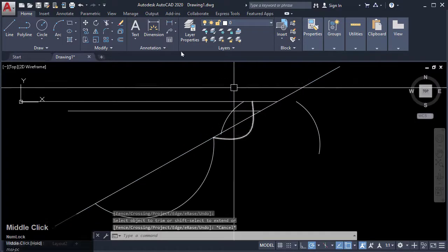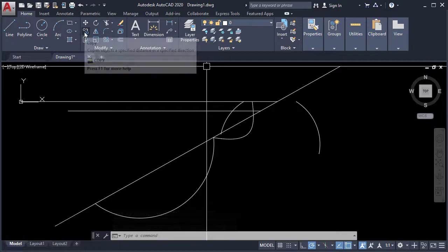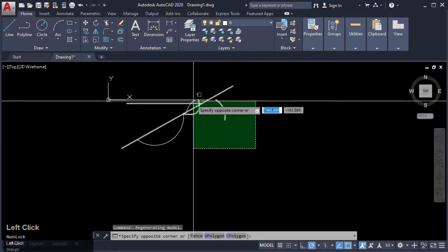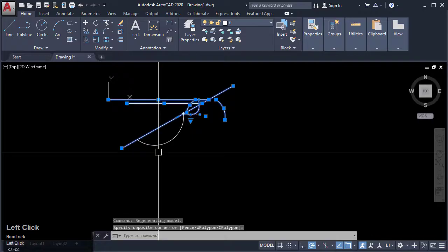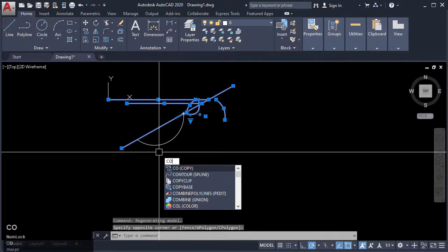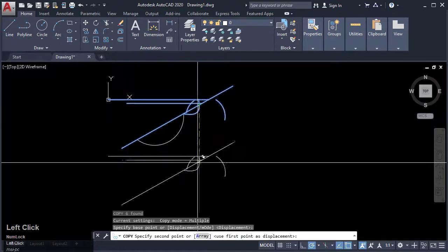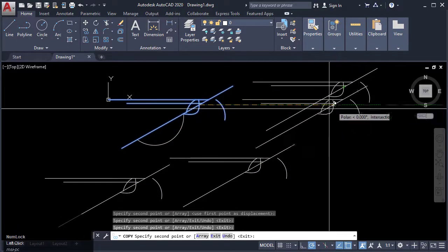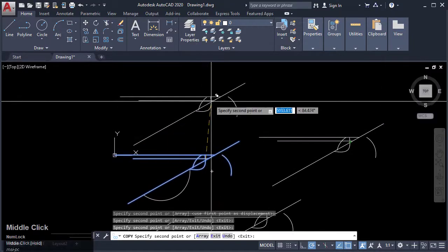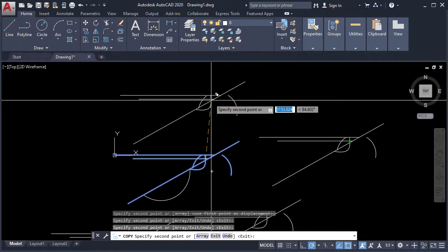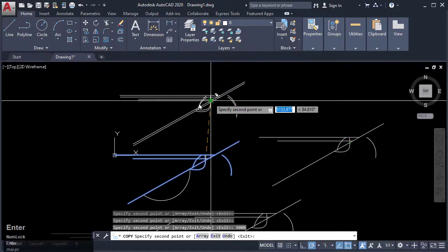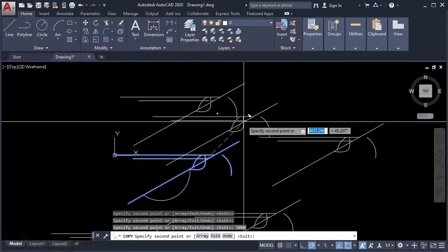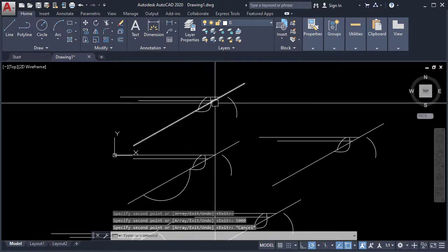Another thing that we can do is we can use the command copy. So if I select an object, then type in the word CO, enter, I can click and drag and click towards the desired location, or I can type again the distance of where I wish to direct my object. So I type in 5000 towards the direction, enter, escape to end the command.